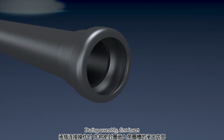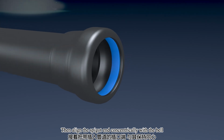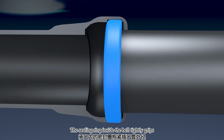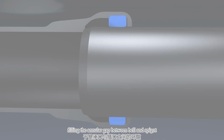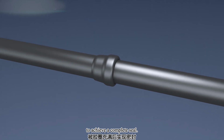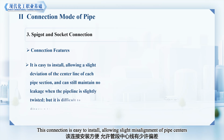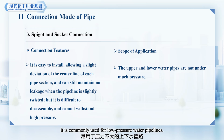During assembly, first insert the sealing ring into the grooved bell end. Then align the spigot end concentrically with the bell and insert it. The sealing ring inside the bell tightly grips the outer diameter of the spigot pipe, filling the annular gap between bell and spigot to achieve a complete seal. This connection is easy to install, allowing slight misalignment of pipe centers and tolerating some twisting, but it is hard to disassemble and not pressure resistant. It is commonly used for low-pressure water pipelines.